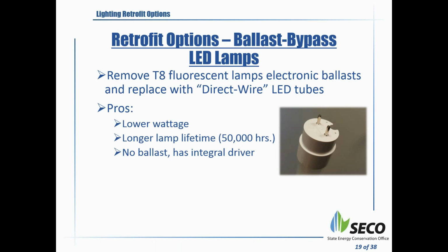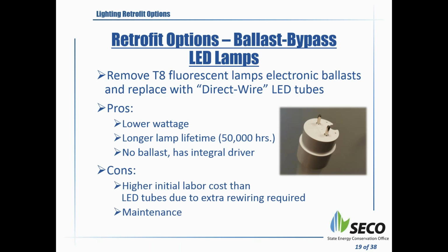So the pros of this one is, again, lower wattage, the same as a standard LED lamp. No ballast, has an integral driver. The cons are the higher initial labor cost than LED tubes due to extra wiring required. If you want to retrofit your fixture and get rid of the ballast, you'll have to hire an electrician, because only an electrician can do that. They will dismantle the ballast, rewire it, and make it ready for this type of application.